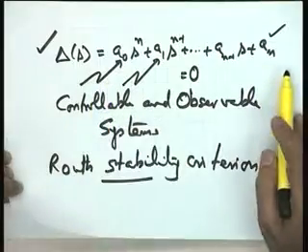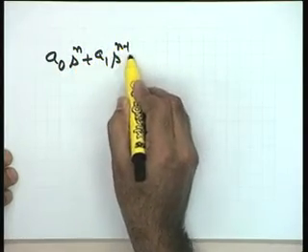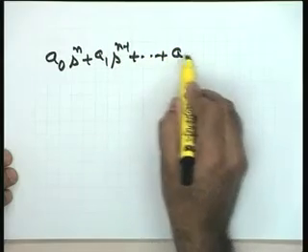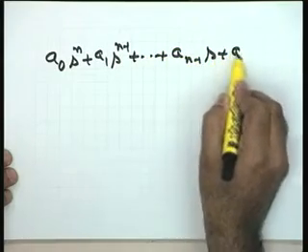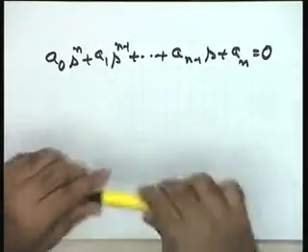Okay. So, my today's discussion is primarily based on the use of Routh stability criterion on stability analysis of a system with a given characteristic equation. So, let me rewrite the characteristic equation here: a naught s to the power of n plus a 1 s to the power of n minus 1 plus a n minus 1 s plus a n equal to 0. Okay, just see that one general statement I like to give, which does not kill the generalization.